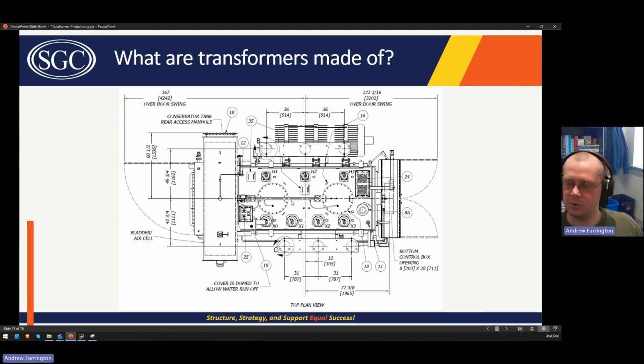There's no orientation on this transformer where you could ever have the bushings H3, H2, H1 if the high voltage winding is towards the top of the page, right? The only way you could do that is if you actually took it and flipped it over, right?